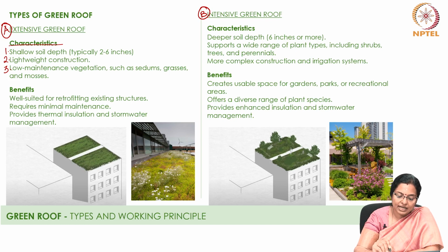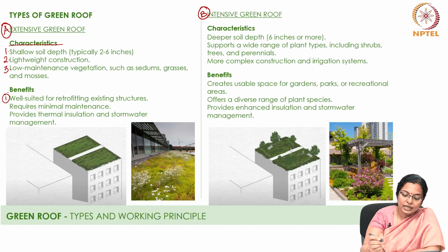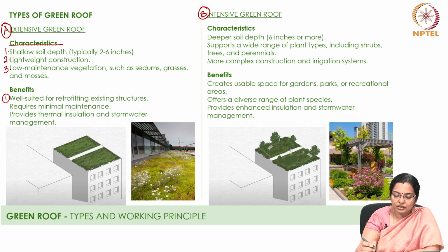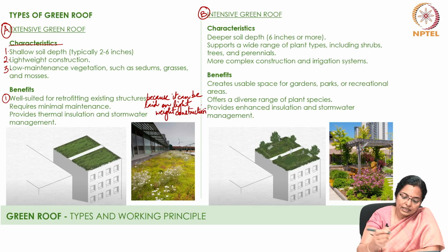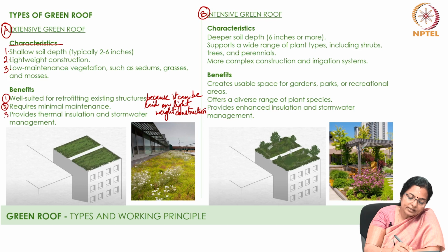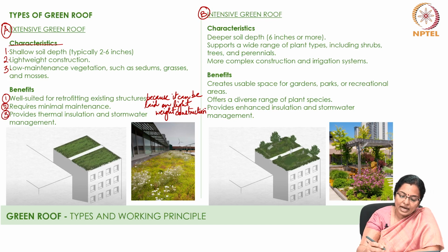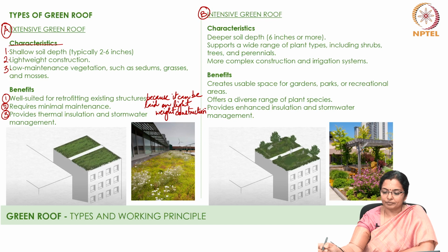Its advantage is that it is well suited for retrofitting existing structures because it can be laid on lightweight construction, which means the dead load is very less. It requires minimal maintenance and it provides thermal insulation as well as stormwater management.